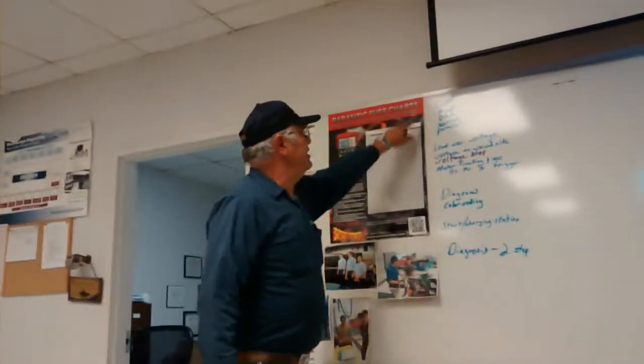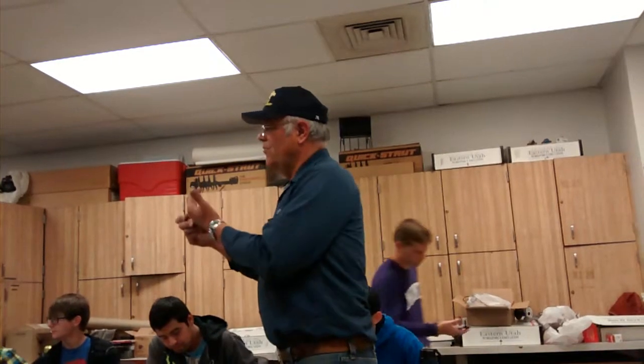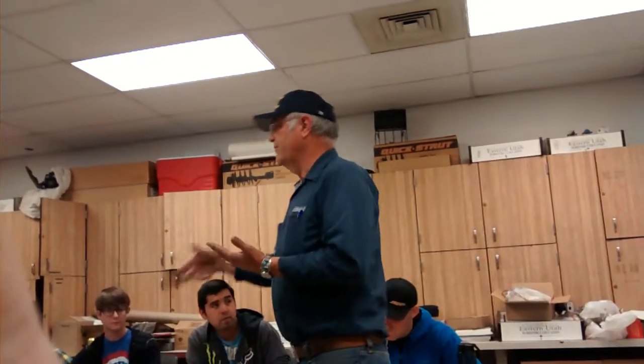Now, the second function of electrical is amperage. Amperage is the amount or flow. It would be like gallons per minute in a water system. Okay, we have to have the correct amount of flow to make something work. So if we have a motor, for example, that requires 10 amps for it to run correctly, and the system only has 5 amps because we have lost the push and we can't push the flow through there, the fan's going to run slow.